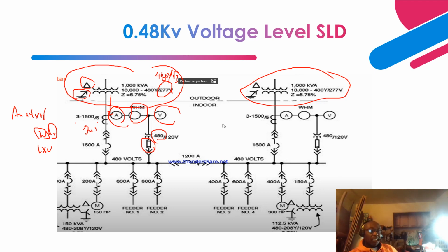Okay, so this is the incomer breaker. The size of the incomer breaker is 1600 amps. So this is a dedicated incomer or a main breaker. Depending on if it's oil and gas, mainly they call it incomer. Then this is the rating of the bus, right? And the tiebreaker, the rating of the other bus. Okay, so bus A, bus B. Redundancy is there, and basically this is the feeder that goes to a motor, and another feeder, and this is the size of the breaker, and the size of the breaker, right?